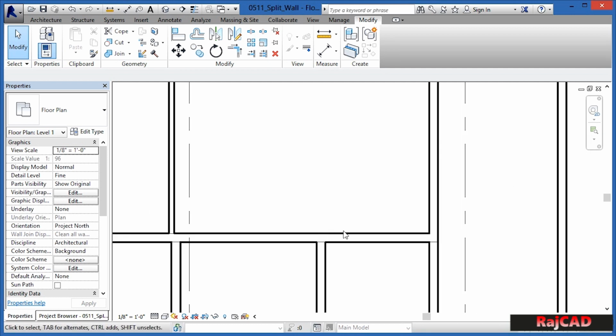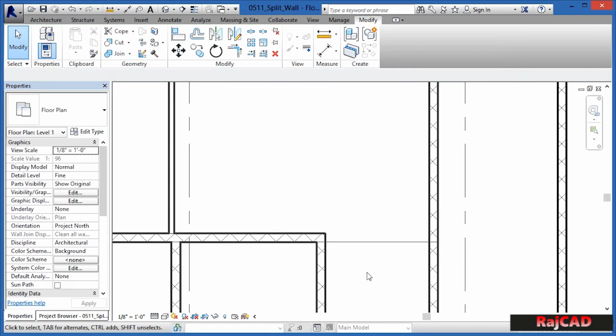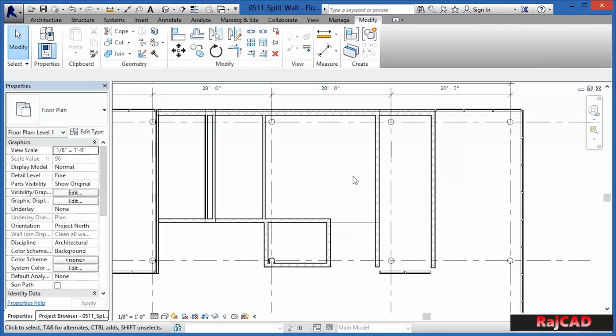And by doing this, we can now select on the right-hand side and then hit the delete key on the keyboard to delete that inner wall segment that was there. So the split tool allows us to either delete the inner segment between two spots that we pick, or by clearing out the check mark for deleting our segment, it'll split a wall up into one half and then another half.